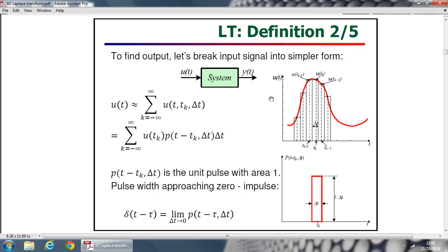The convolution integral comes from the idea of the response of a system to an impulse input. To estimate the response of a linear system subject to a random input, we can assume that the input is a summation of consecutive impulse inputs, and the output of the system, according to the superposition concept for a linear system, is the summation of all responses subject to these consecutive inputs.